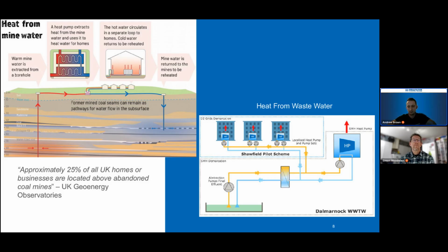We had a lot of conversations with the client, looking at water sampling data and whether our standard offering is suitable. So we ended up supplying 2 filters with super duplex internals for protection of heat exchangers, and also downstream water treatment equipment.